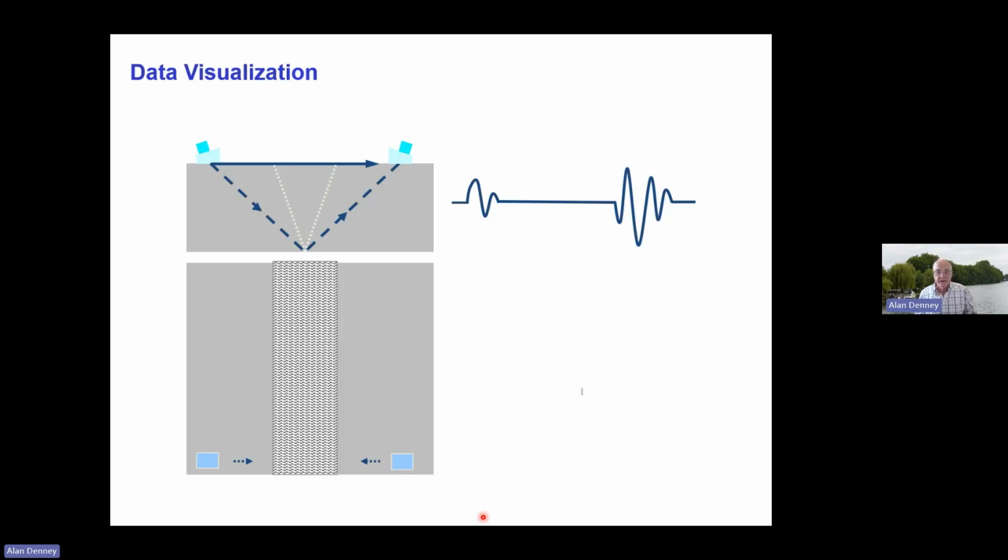So that diagram is familiar on the upper left, but you've got the lateral wave and the back wall echo showing. What you're seeing on the bottom is the length of the weld, and the lateral wave and the back wall echo, and the peaks and the troughs. The black and the white correspond to the peaks and the troughs.